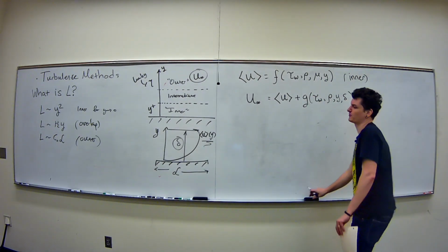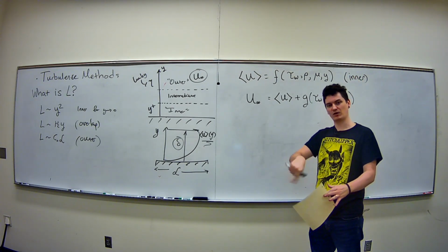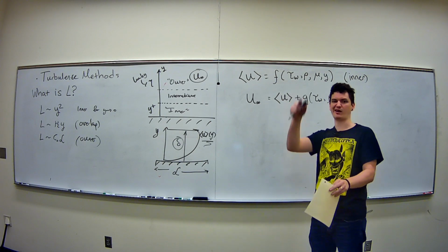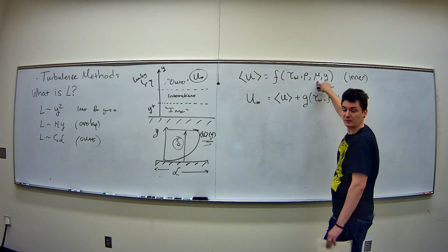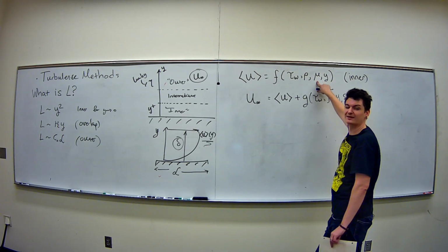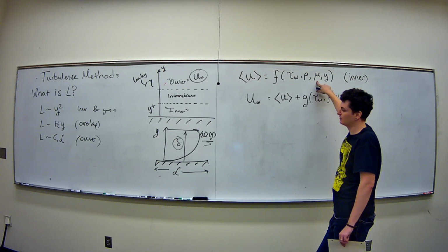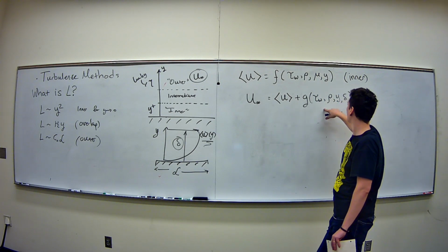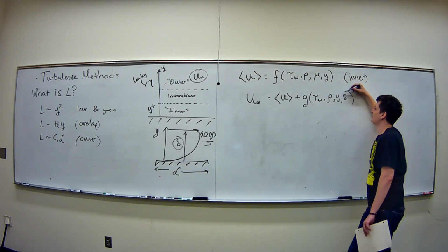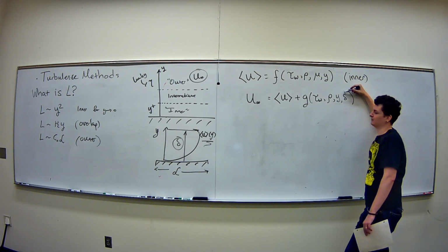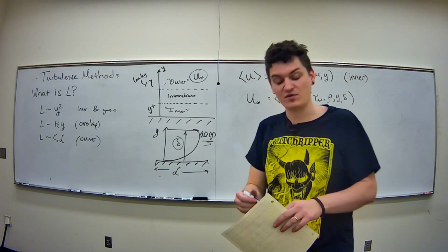So you think more about vorticity in turbulence because if you look from above at a plate that has gone turbulent, you'll see oil slicks having all these vertical lines just shooting off. So that's critical. But the inner wall you still know is going to be governed by viscous forces because no slip still has to be obeyed. So the question is, what's this length scale? Right close to the wall. And then far away, you don't have viscous forces mattering anymore. There's some length scale where the viscous boundary layer has ended, and now viscous forces do not matter anymore.